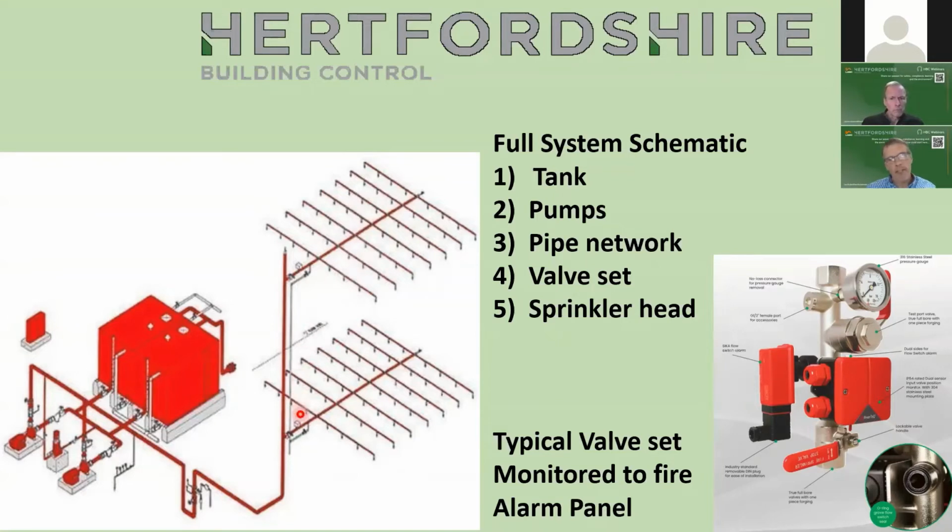It's no different to your HVAC. If that was an HVAC, there'd be a volume control damper there. So that one would be closed, or 3/4 closed, and that one would be fully open. So it gives you kind of an idea how these fellas are balanced up.